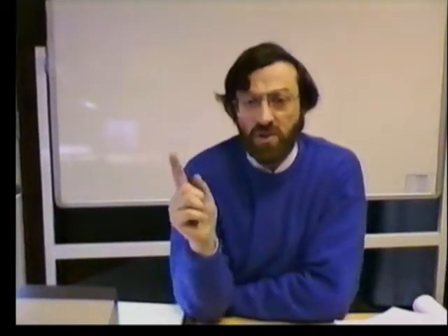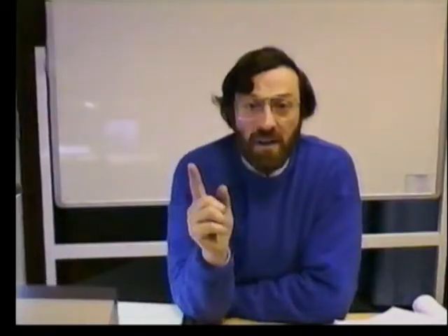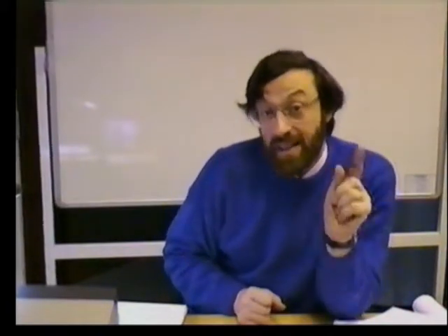What are we going to do about it? If you had a feedback system, it wouldn't matter. Feedback controllers inherently cope with all changes because they're always monitoring the actual true outcome, the error. It always measures the output. So if we find that a particular valve isn't operating as it used to be, the control signal will adapt for that. It will adapt to changes. And so a feedback system inherently overcomes long-term drift because it's always monitoring the truth, the output.